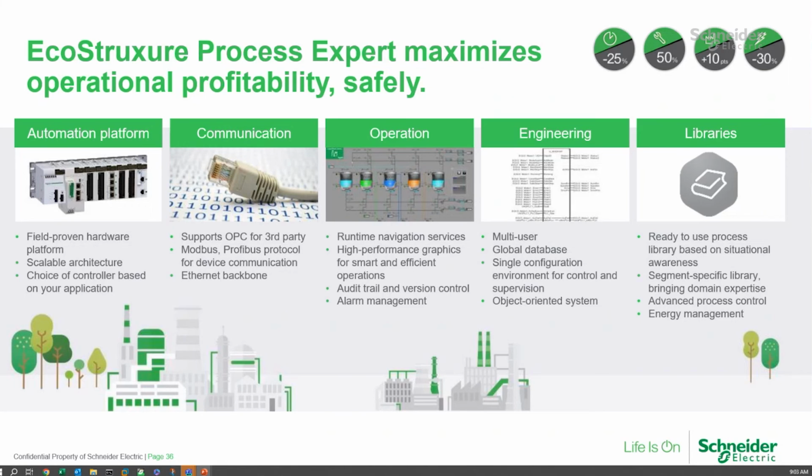The runtime navigation services and the operation really enhance what an operator normally sees there, just as a control pop-up. But it gives them so much more information about each individual piece of equipment or asset that's in the system. And so now you can really embed all of the knowledge base that you have for a piece of equipment or a part of the process within the supervision system automatically. So an operator, just a few clicks away, goes and grabs whatever manual or whatever drawings or document, or goes to whatever web page is appropriate to help them out.